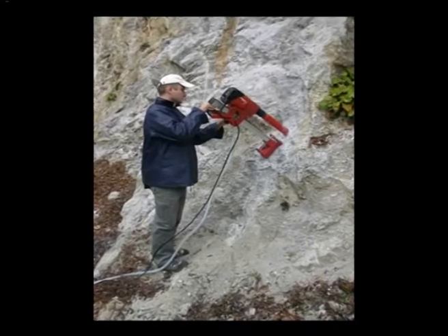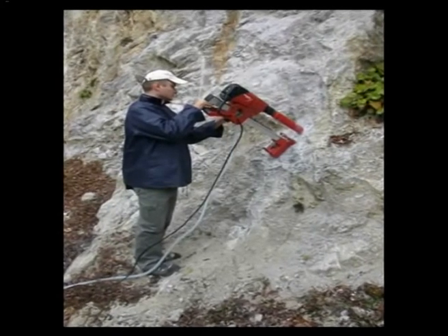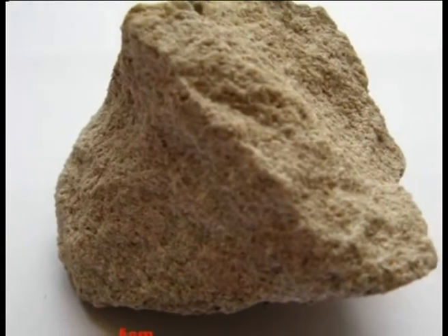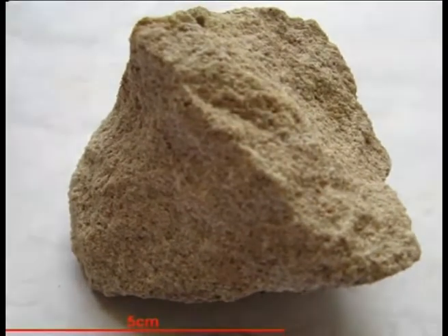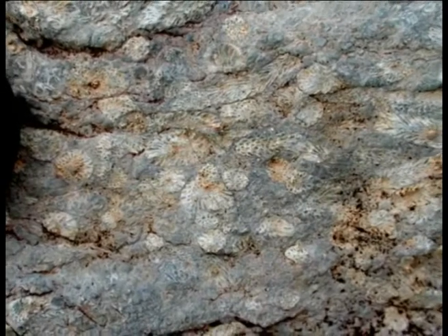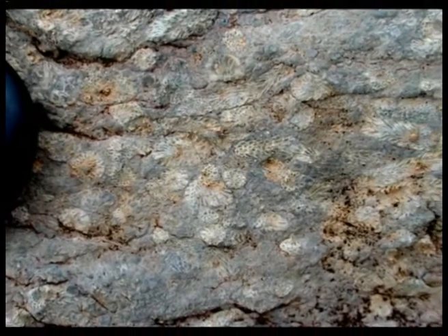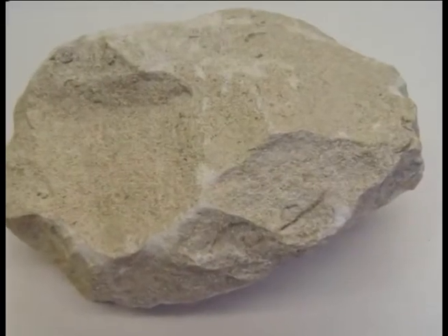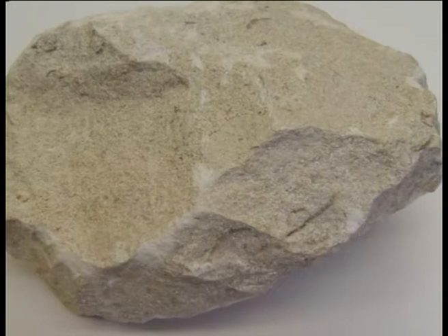Limestones. These sedimentary rocks are also very extensively used as building stones, but not all types are suitable for this purpose. They vary greatly in their physical properties. In crushing strength they may be as weak as showing values much below 300 kilograms per square centimeter or as strong as 1500 kilograms per square centimeter or even more. A similar variation in other properties like absorption, specific gravity and porosity may be observed.